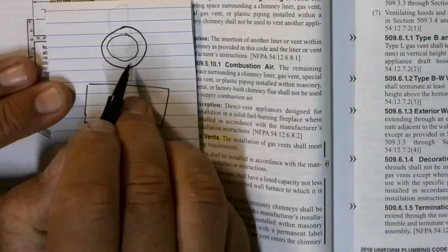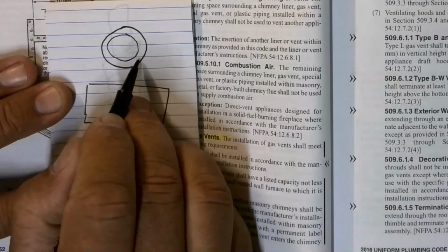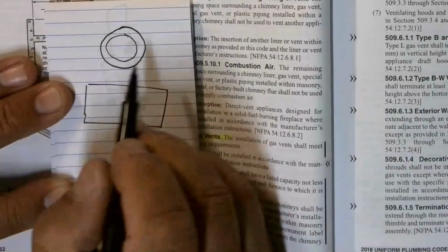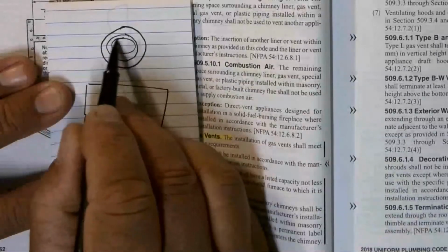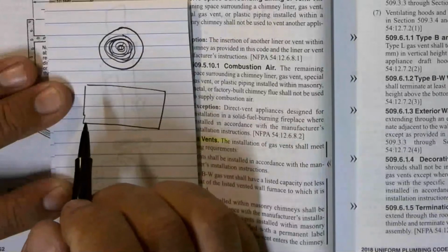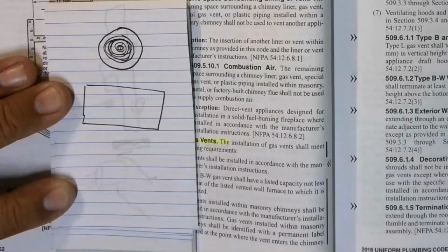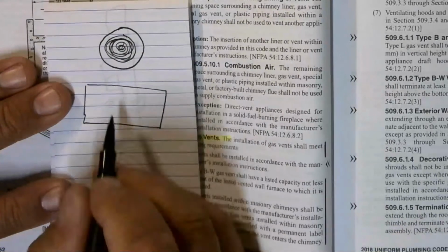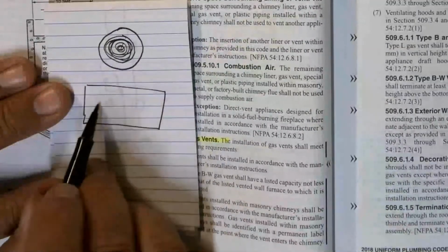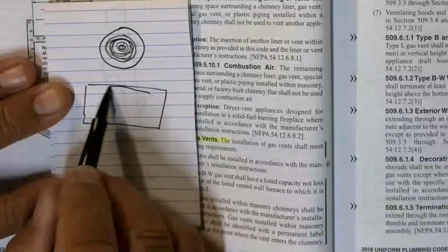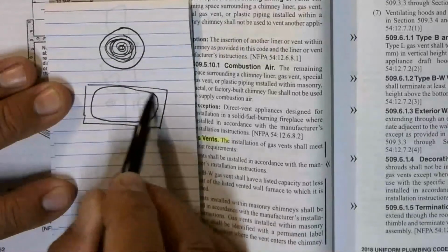design, because this outdoor air, this outdoor section here, actually acts as an insulatory agent to where it draws the heat on out of the ducting. It just draws it right out. It's crazy how it works. It's kind of cool. So a BW is a B vent, but designed to go inside a stud bay, and it's oval in shape.